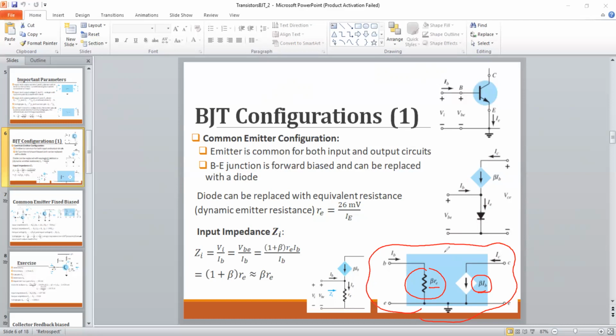So previously we discussed how we can get the AC equivalent circuit. So then we can simply replace the AC circuit's transistor with this transistor model. You can just remove the transistor in the circuit, because during the previous discussion we got that AC equivalent by keeping the transistor model as it is. We just applied the conditions and simplified the rest of the circuit by keeping the transistor as it is. Now what we can do is replace this transistor with this RE model.